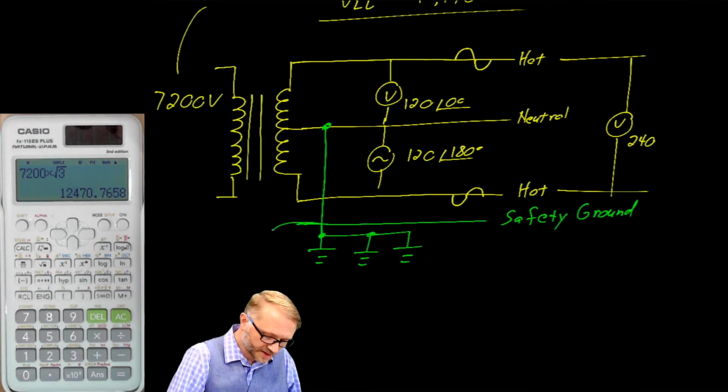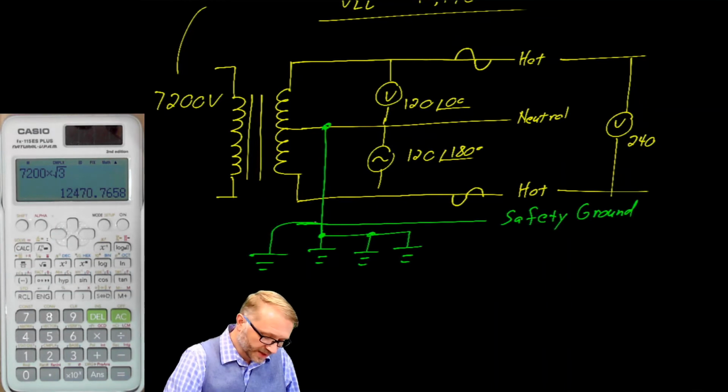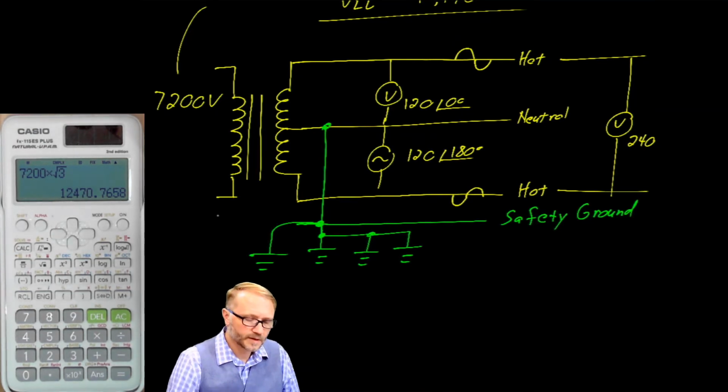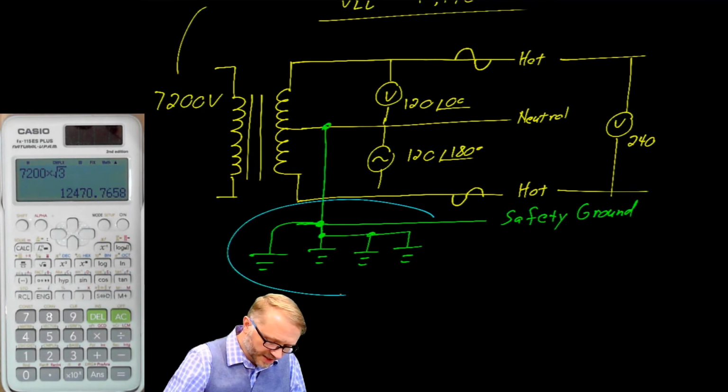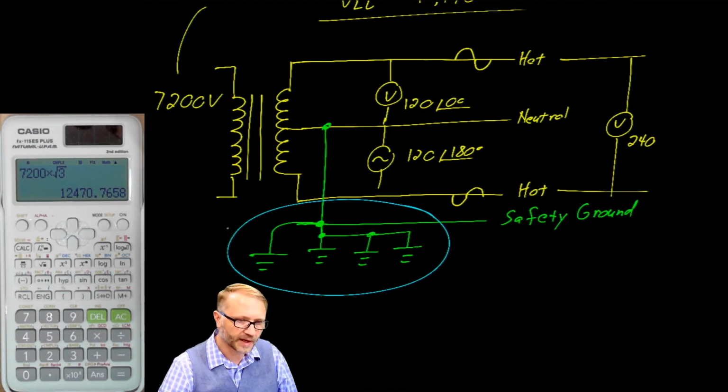You may also see a connection from ground to the plumbing of your house. For example, if you have a water pipe entering that's metallic, you'll typically have a connection going to your breaker box to that. You'll notice there's a certain amount of redundancy built into the system, and you'll also find that your building inspectors are really fussy about how these connections are made because they're important.